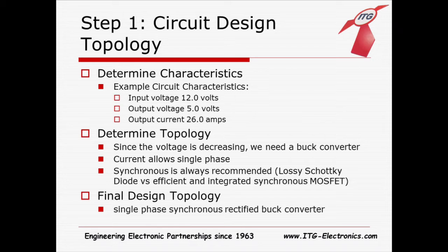Obviously the synchronous allows for a much higher efficiency, so that's most of the reason that we recommend it. So our final design topology is going to be a single phase because we only have 26 amps, synchronous for efficiency, and buck converter.